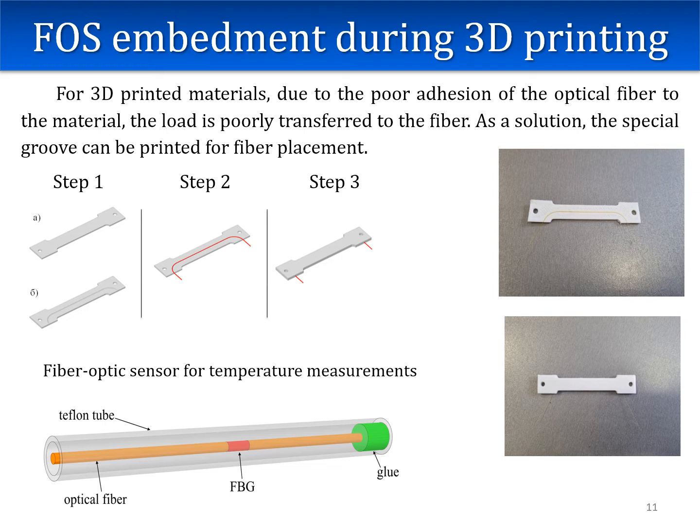In our case, a special groove was used for the fiber placement to improve adhesion between the optical fiber and the material. To measure the temperature, it is proposed to use an optical fiber with a point or distributed sensor enclosed in a hollow Teflon tube.